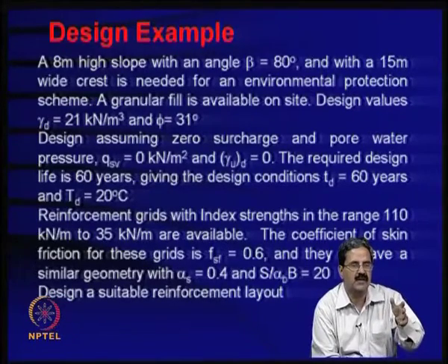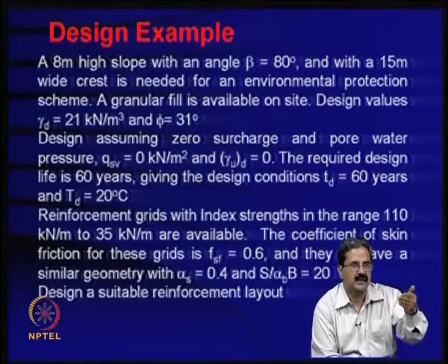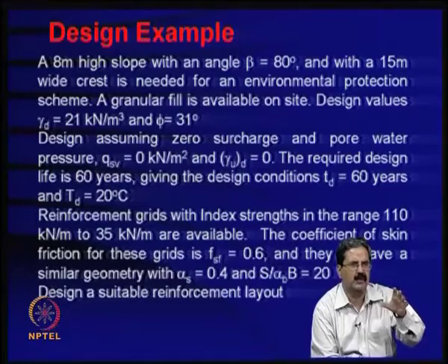So, once you do that, you will get that equivalent height, like nothing but it is like Q is 20 kPa, Q divided by then the bulk density, say for example 18, 20 by 18 will give you the extra height, say 1.1 or whatever.